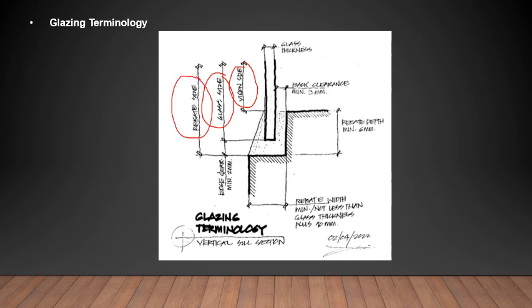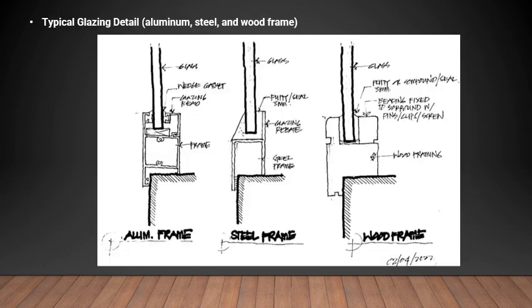These are the important dimensions that need to be considered in preparing shop drawings or production drawings, in detail, installation drawings. We also need to consider the edge clearance, a minimum of 2 millimeters, depending on the setting blocks. Normally it is 5 millimeters or 6 millimeters. Now, what is the glass thickness, and what is the clearance behind the glass, the internal. So the rebate width is a minimum of not less than glass thickness plus 10 millimeter. All right, so next is the typical glazing.